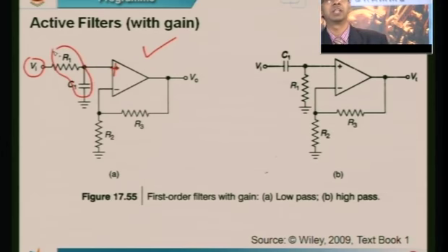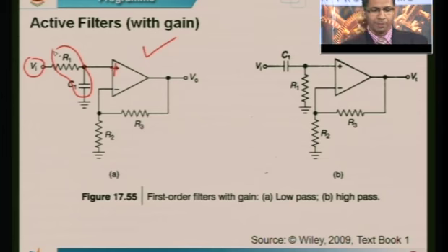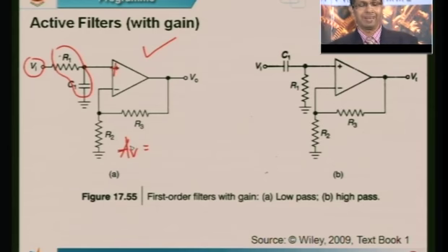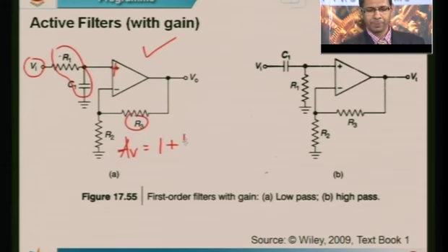This is a non-inverting amplifier wherein the gain is given by the equation. Anyone remember the equation for a non-inverting amplifier? Yes, the gain is given by 1 plus the feedback resistance, which is R3, divided by the input resistance, which is R2. When I say input, I am talking about this feedback path at the inverting point.